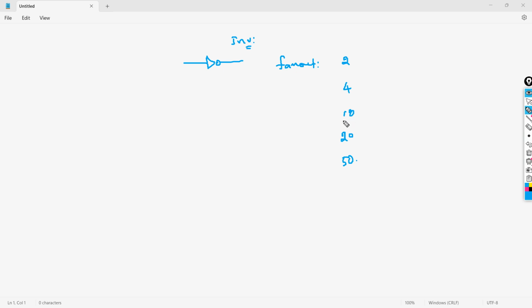You cannot use a simple inverter, or a lower drive strength inverter, to drive a bigger load. So to meet the PPA requirements, what the libraries team have developed is something called drive strength. That means you will have multiple drive strengths. I'll just show you guys in the library itself so that you get an idea.